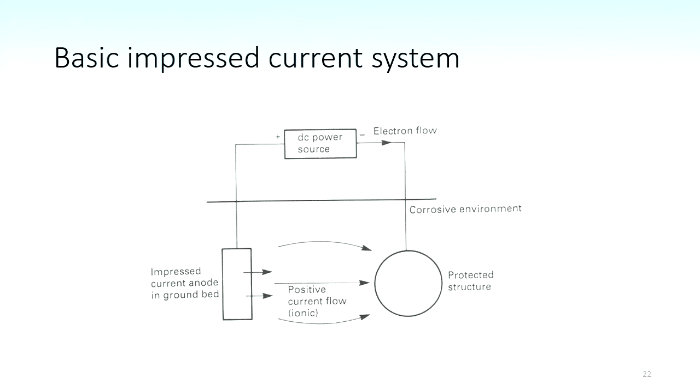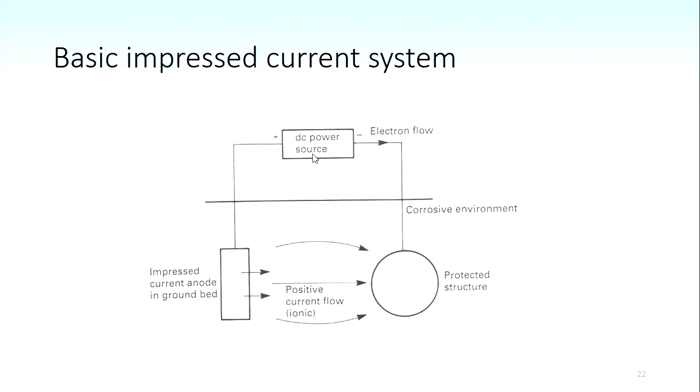So really, the anode-pipe distance. Instinctively you'd say, oh well, to keep the resistance down, we'll put the anode and cathode close together. But in fact, in order to get a more even current distribution, you have to move the anode and cathode apart a bit. Yes, sir. The bigger the pipe diameter, the bigger the installation.